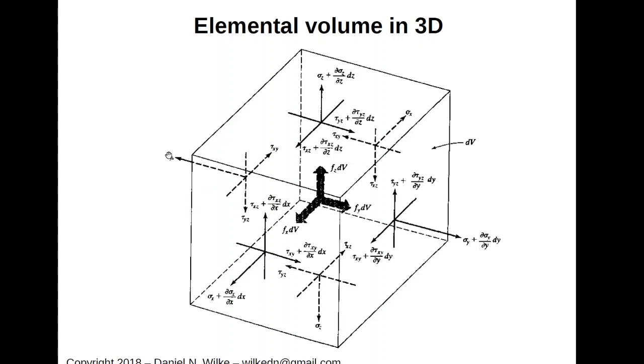And if I go towards the left-hand edge here, sigma y, with the shear components acting on this face, as I move across the body here, there's again variations because I've moved now in the dy direction. All of the variations in terms of dy could have caused the stress that was a certain magnitude here to be slightly larger or smaller, depending on what kind of stress field we have, loading that we're applying. And so essentially, if I go to the bottom, the same story holds. Okay, so that is really what this boils down to.